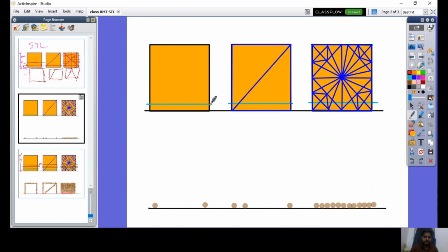So the CAD model will have only two edges. When these edges are intersected with the plane, the intersection point between the imaginary plane and the model edge is obtained through a calculation in software. So the position of the first intersection point and the position of the second intersection point will be sent to the machine, and the machine will go to the particular position.